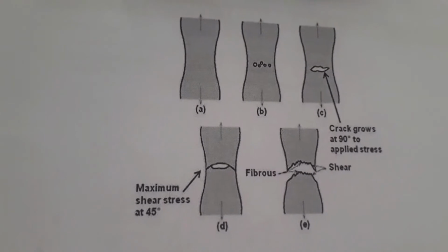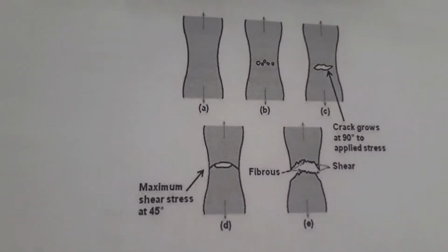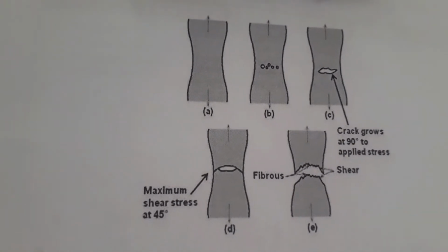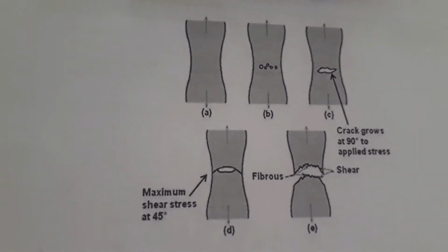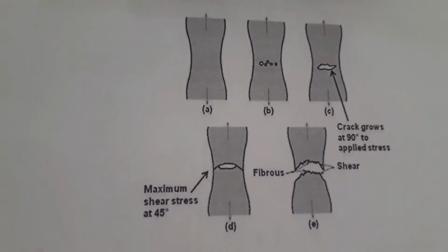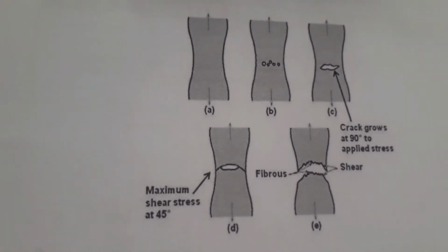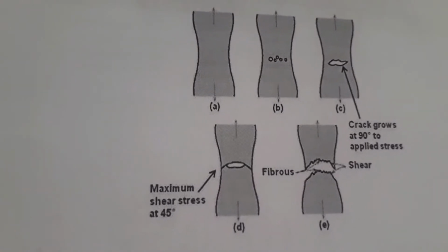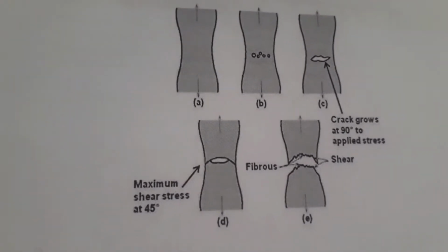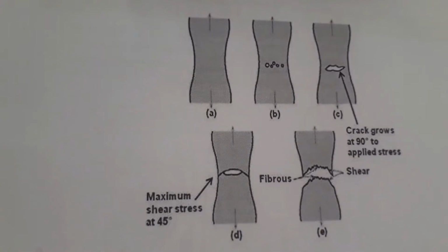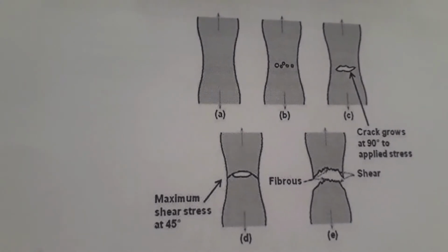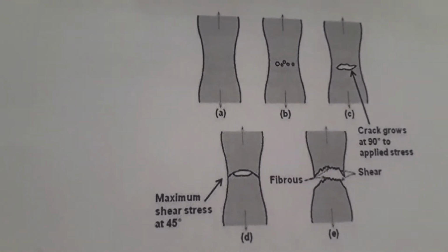Apart from necking, the voids also cause the metal cross section to reduce. The stress now acts on an increasingly smaller cross section, which enhances the process still further. As the tensile test continues, the necking increases until the tapered cross section can no longer withstand the stress. This is when the metal bar tears at the weakest point. Finally, the specimen will have increased length and reduction in the cross sectional area.